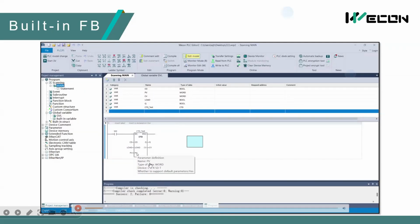For example, this PV is data word. So here we need to create a variable and set its type as word. So then we can bind that variable to this PV input.